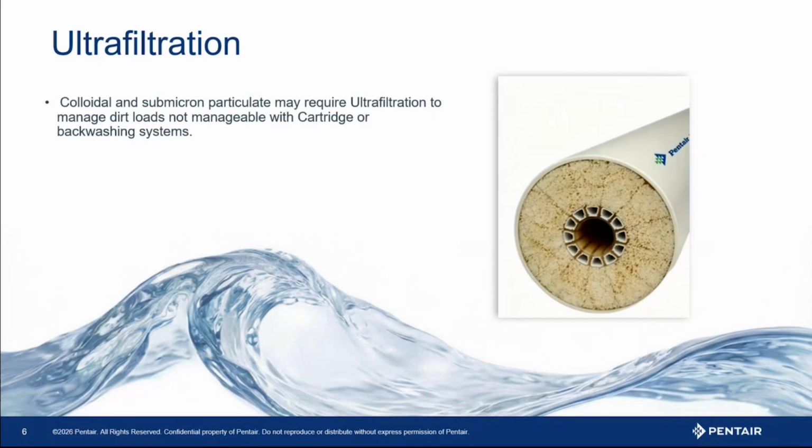And also be aware, if you're doing iron removal, understand that pH above 8.5 is going to cause that iron oxidation that you're doing to form very, very fine particulate. So you may be creating another problem for yourself while solving one. So remember, how we do these things impacts the next step.